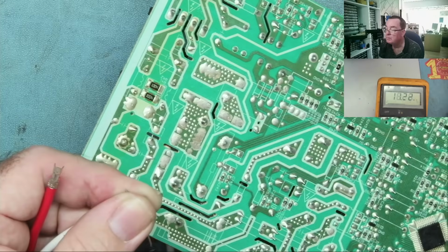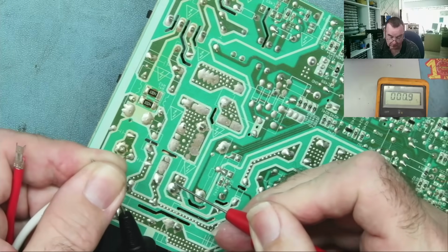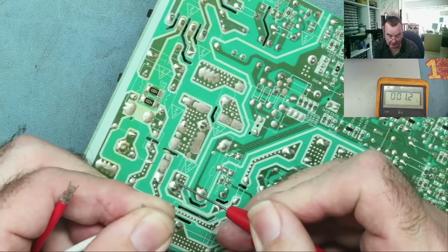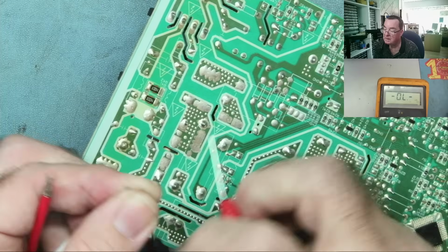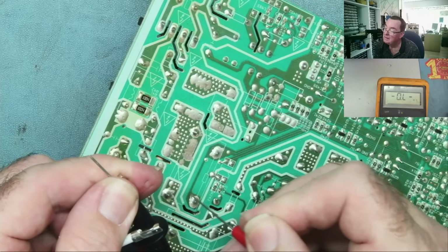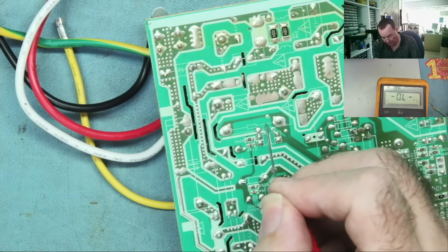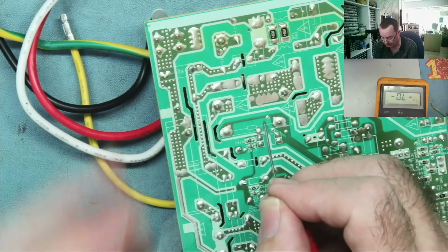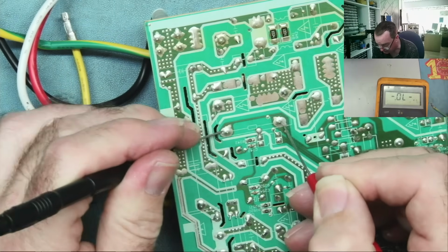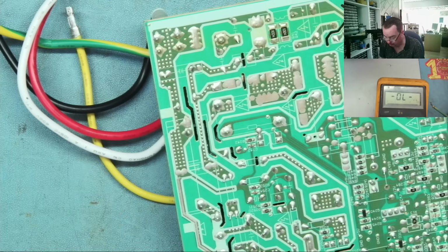Yeah, megaohm. That one connects to there, and then probably the other one doesn't connect to that. It probably switches between them. Okay, and then we see, yeah, so this is the coil. If it wasn't marked like that, we should be able to test if it's a coil, because it'll have a resistance. Yeah, 158 ohms. That's fine for a coil.